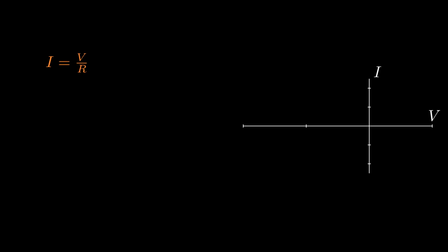Voltage across and current through a resistor are related by Ohm's law. To plot that with the voltage as the independent variable and current as the dependent variable, we need to rearrange Ohm's law, solving it for current. Adding that to the plot, we see a nicely behaved linear relationship for a resistor. Now, when we consider a diode, things are more complicated. To write the relationship between voltage across and current through a PN junction diode, we have to express it as a piecewise function with three distinct regions of the domain.